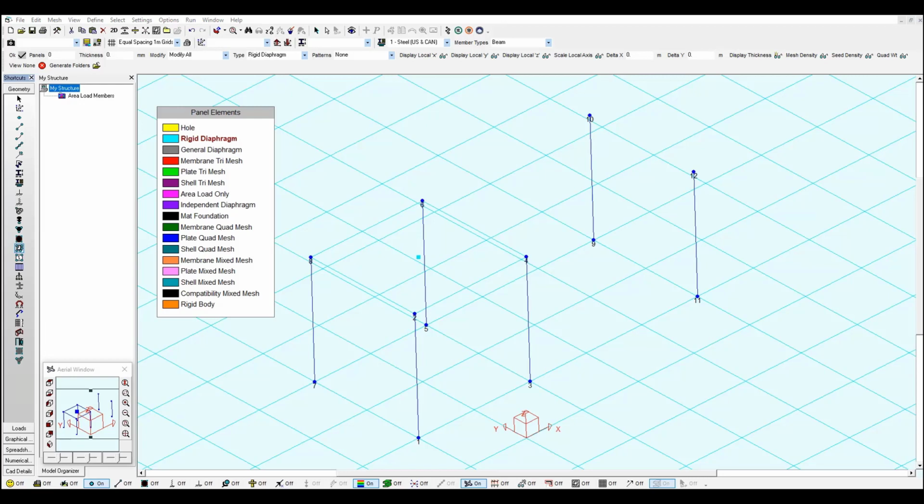The center of mass is supplied, which means that thickness and material density can be defined. Please bear in mind that these properties do not alter the stiffness, but do add mass to the diaphragm in the X, Y directions and rotational mass about the Z axis only. Rigid diaphragms can also be defined as triangular, quadrilateral, or polygon diaphragms using the tools in the geometry window of S-frame.